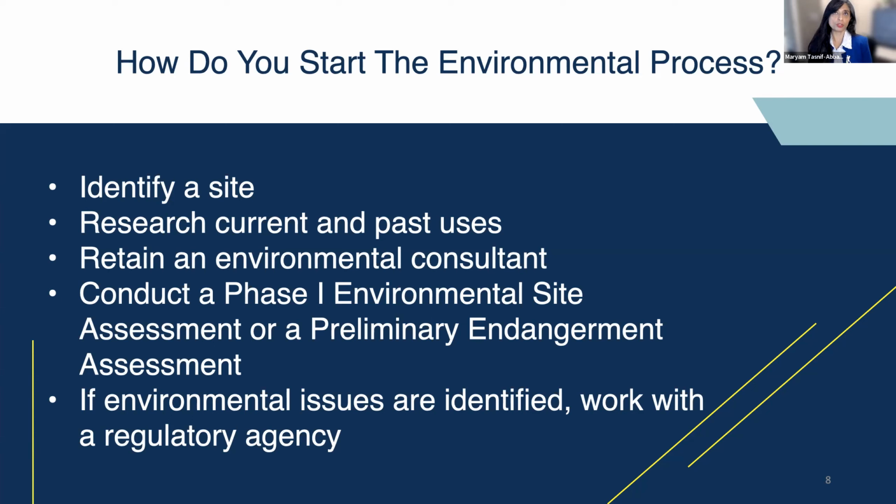If based on doing the research, there is an understanding that there may be some past uses to be concerned about, or uses in the area that cause some concern, bring on an environmental consultant to conduct a Phase 1 environmental site assessment or a preliminary endangerment assessment. These are first stage type of environmental assessments that can be done without collection of samples or anything more complicated, but a lot of desktop research goes into these types of documents to help someone understand what the actual environmental conditions are at their site. And then if environmental issues are identified, then it's our recommendation that you bring on a regulatory agency. Next slide.